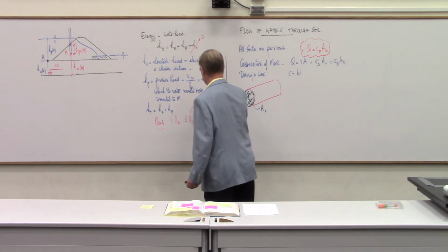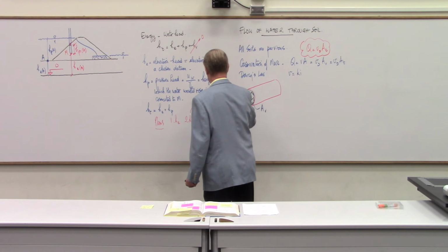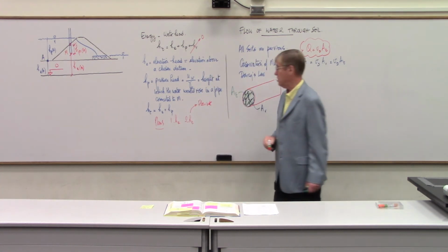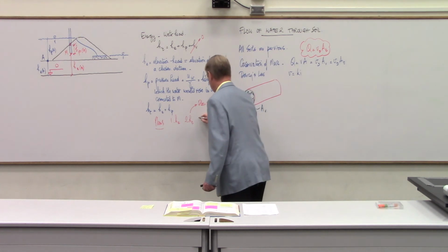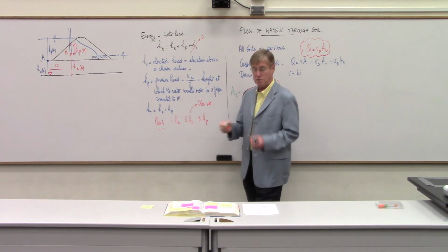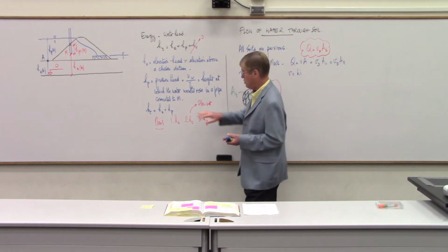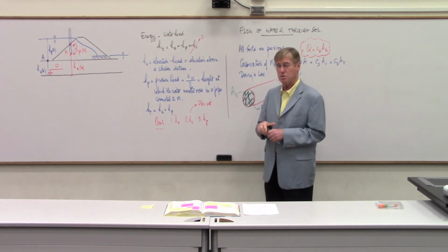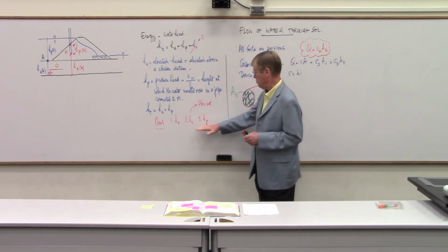All right, so that's another magic thing that we're going to discuss later on. But we calculate H_T through the concept of flow nets. And then three, you get H_P by difference between H_T and H_E. Okay? So I'm trying to give you some step-by-step consistent procedures. This is for the pressure head.